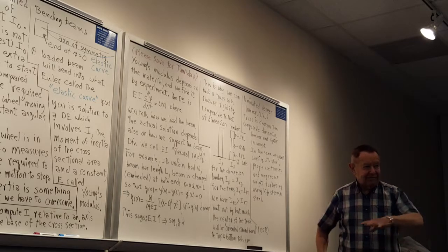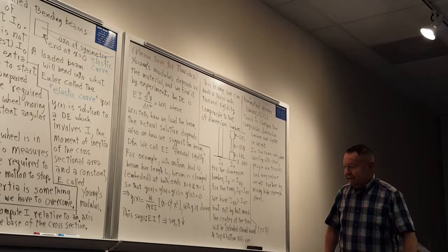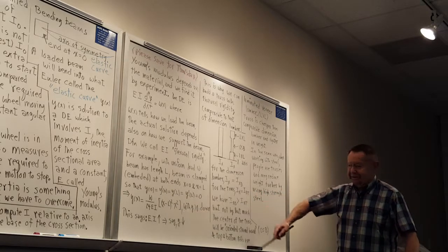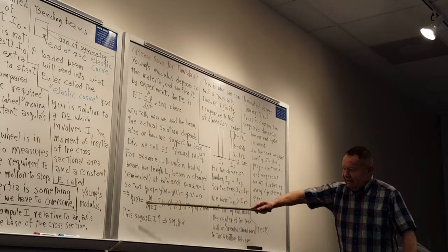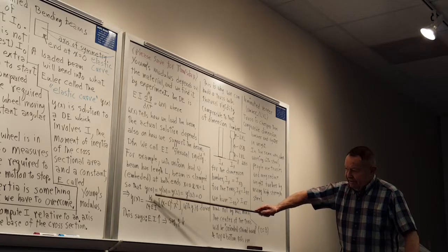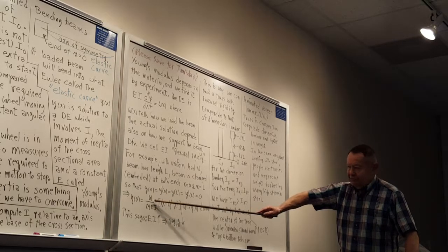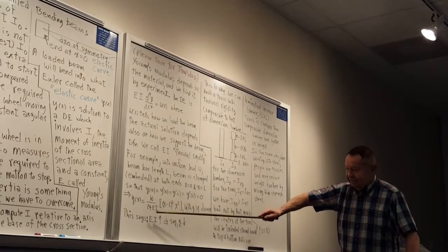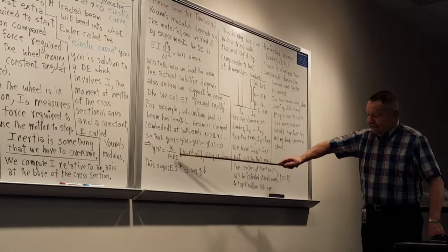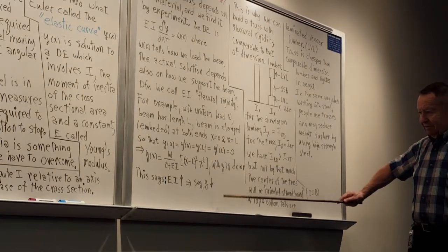You can certainly have other kinds of boundary conditions, but if you happen to use those to make something that's easy to solve, you get a solution for your elastic curve, where I'm assuming a uniform load, so the W is constant and the E and I are constant, and so it'll look like this, where Y is positive down.